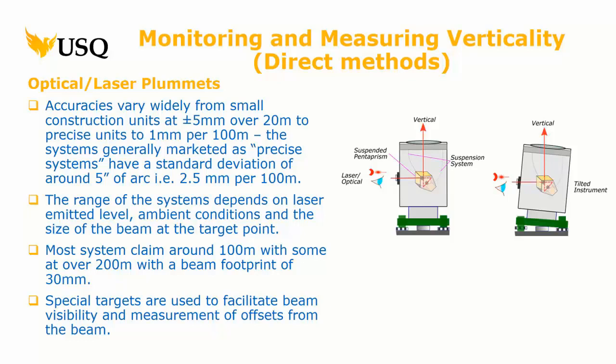And the beam footprint, which is the divergence of the beam, you don't often see in surveying because most of you work in daylight, so you don't actually see the laser beam. When we stuck one up in this room, a cheap laser, it would probably be about 50 mil on that wall, about that sort of circle. I don't know what current total stations would be, but I'm presuming a lot less. There's a figure in 2301, I think, we did for the divergence of the beam. It's important because if you're measuring vertically and someone's measuring it on the top, too wide a divergence means too much range of error.